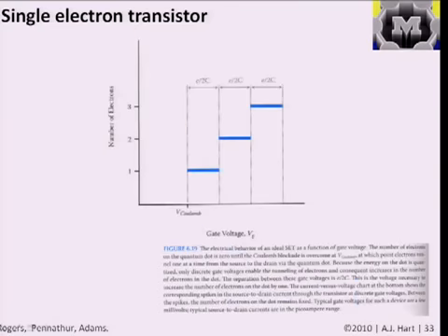And on this plot, we see a representation of the physics of an ideal single electron device, and in some ways certain devices made agree with this very well. And what you see is that the separation between the values of the gate voltage needed to store a different number of electrons on the device are related to the fundamental charge of the electron e and twice the capacitance of the dot.